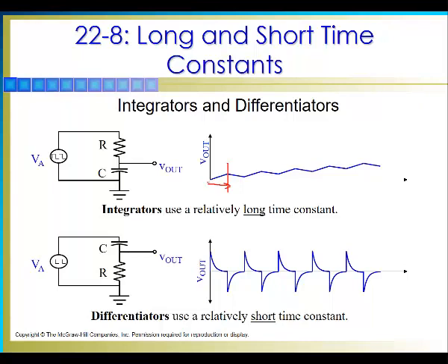The voltage is being applied on and off, but the time constant of the circuit is very large. So by the time this one might be very small compared to the time constant, the voltage on the capacitor will start looking like a constant voltage.